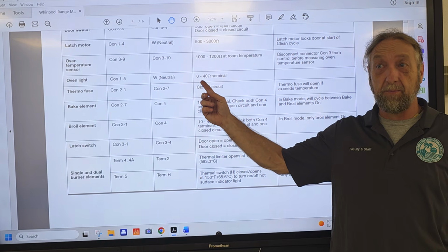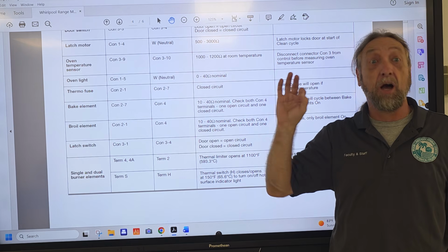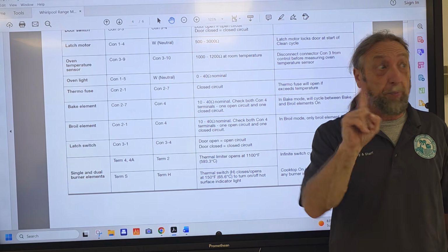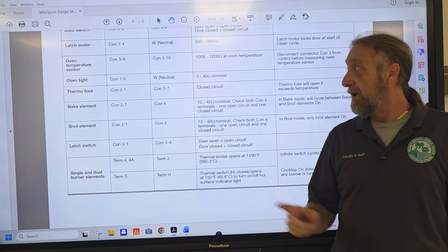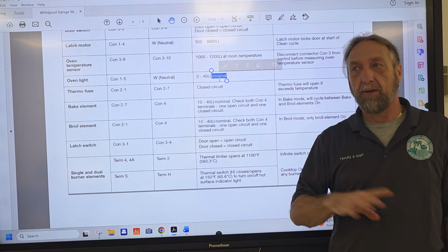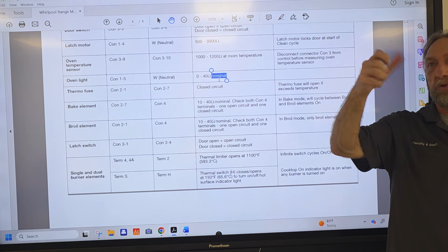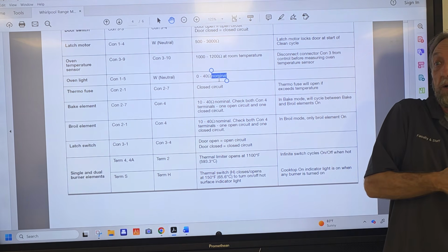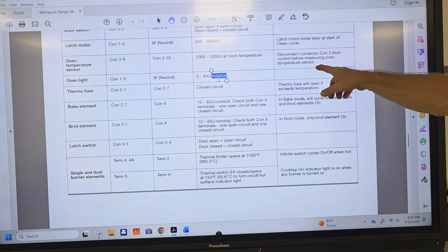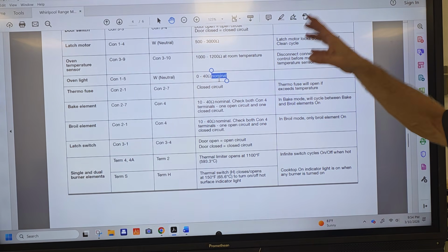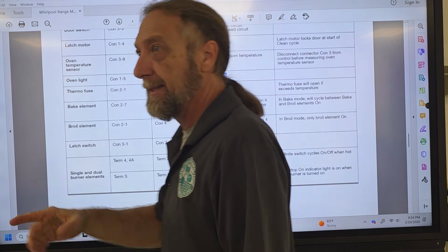They never have zero. Because if the light bulb read 0 ohms, what does 0 ohms indicate? A short circuit. Low resistance. Not an open bulb, short, but there's no resistance there. If you turn it on, it's going to blow the circuit breaker. So this 0 to 40, that's not correct. You might get an infinity reading for 40, whether the light switch is on or off when you're doing the test from the board. But in this case, 0 to 40 is not good. It has to have some resistance. You cannot apply voltage to any load that is 0 ohms.